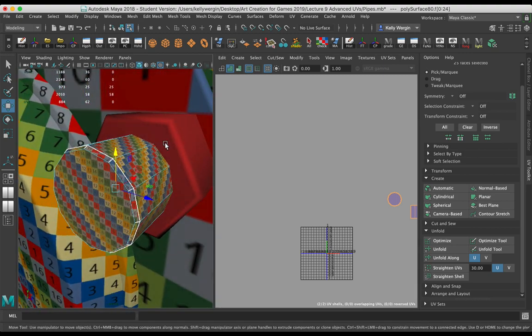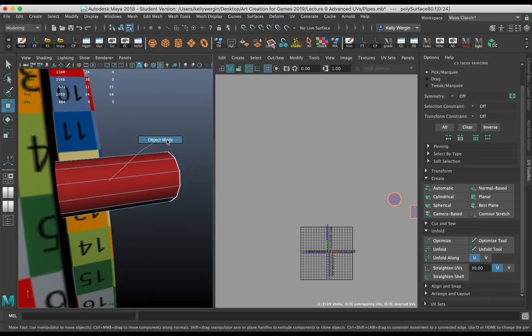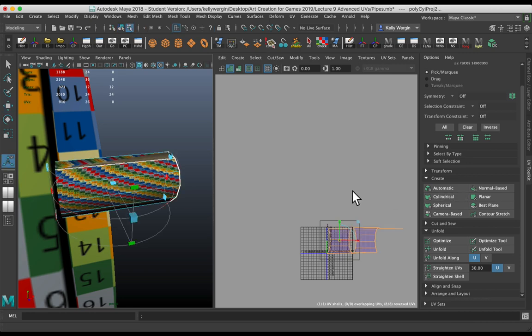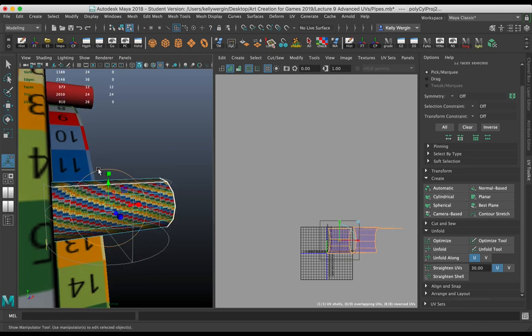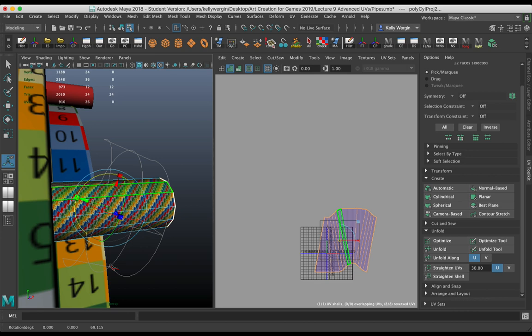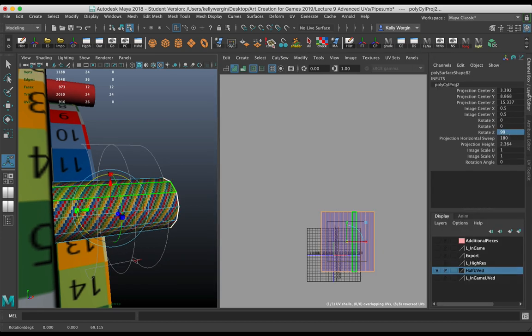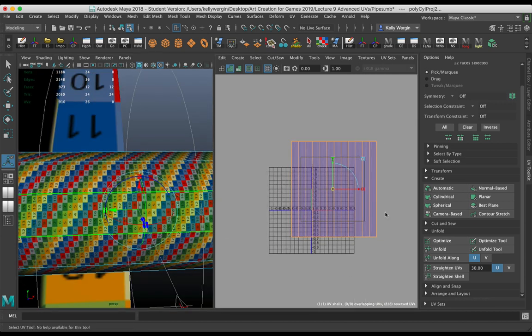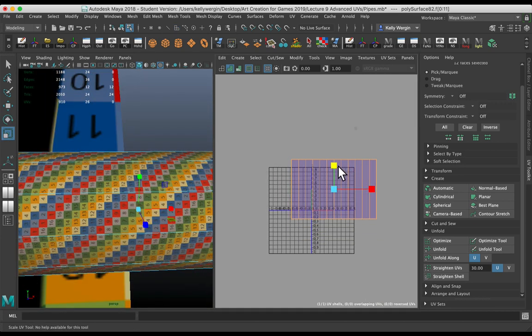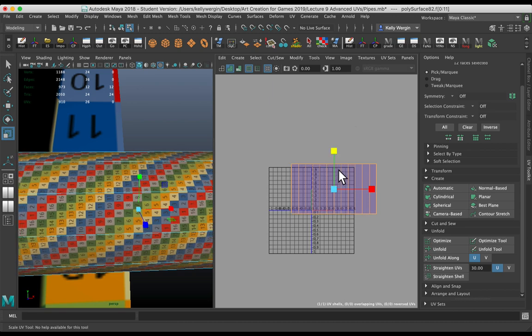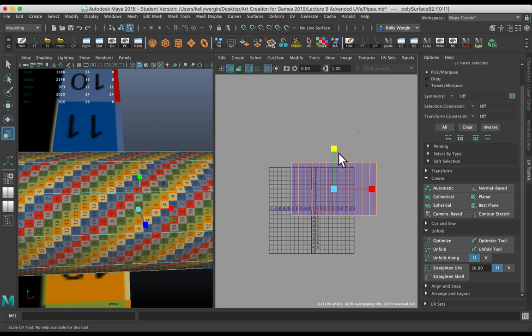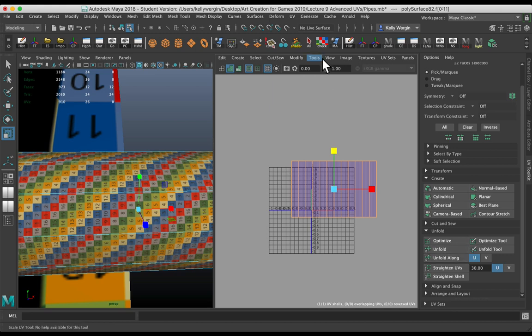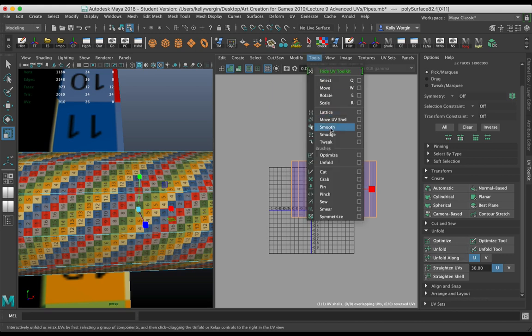This one in the back is also just a basic cylindrical map. So I'll do that. Grab the T to edit, grab the rotate widget, and rotate. I'm just going to type 90 in, because I'm pretty sure that's the right angle. And this definitely needs to be scaled a bit. Stop when the checkers are square. This is not something that layout fixes. The only thing that fixes rectangular checkers is you either manually scaling shells, using unfold, using the smooth tool. Those are the tools that stop this from happening.